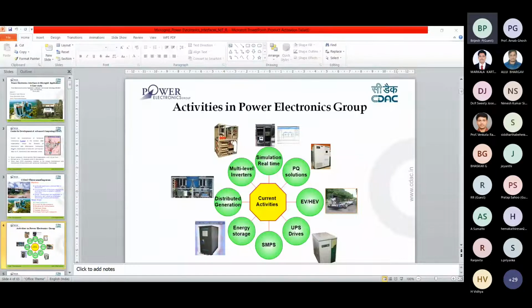So a microgrid has different energy resources. They may not all be renewable resources. You can have even fossil fuels in the microgrid, but we are mainly focusing on the microgrid with renewable resources. The important thing is that the microgrid connects to our grid at a single point, so it can work in two modes: grid connected and islanded mode. This is the basic definition of the microgrid.